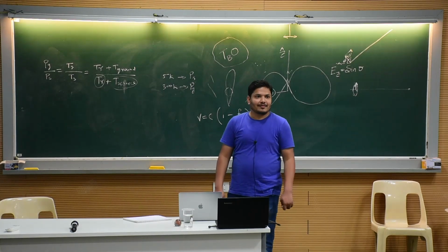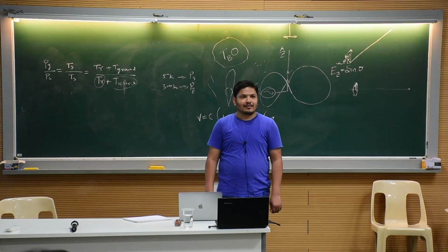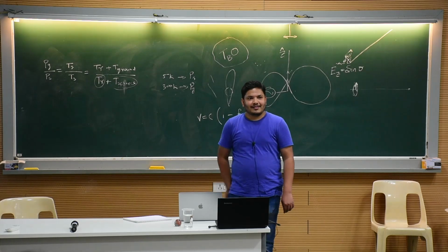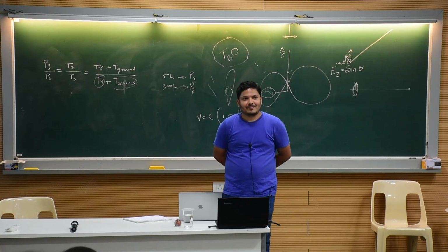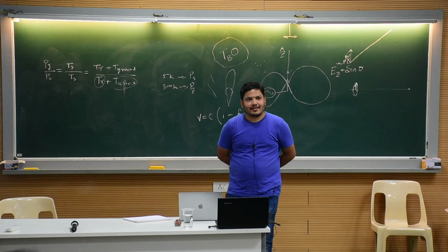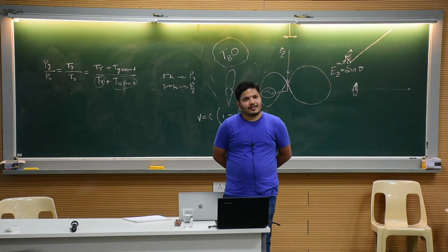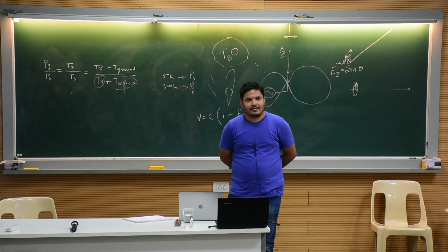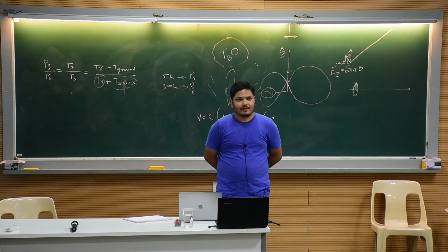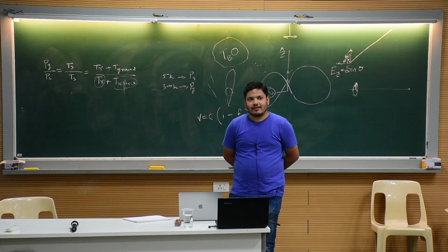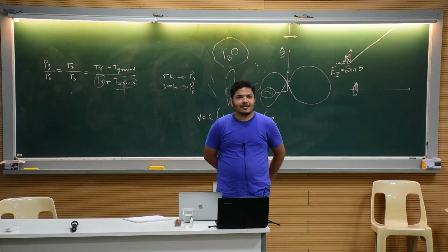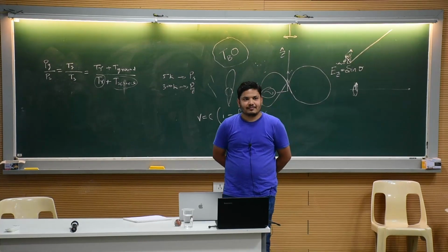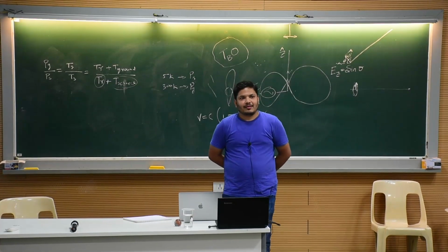Yeah. I just had one comment when you point to the wall to get the 300 degree Kelvin measurement. Let them also move the horn distance to the wall a little bit and check that it's not changing. Because the receiver noise itself will get radiated from the horn. It will bounce and it will form a standing wave of its own. Right. Which you don't want to change.